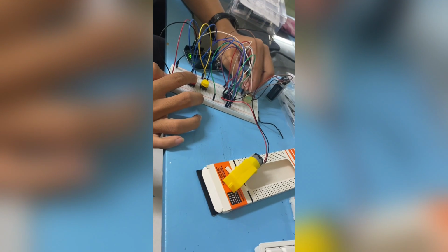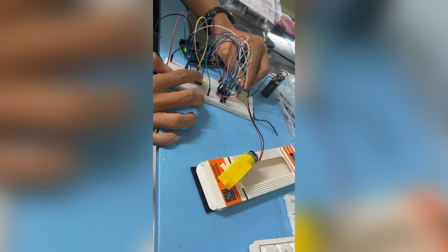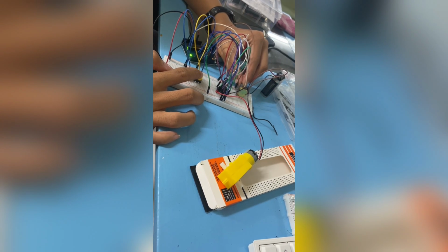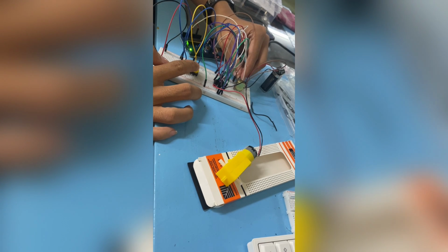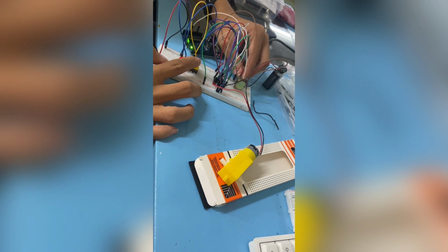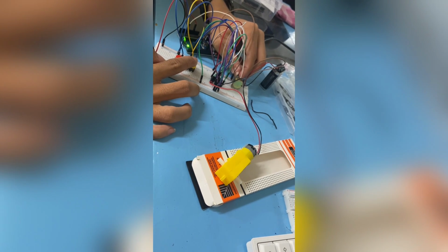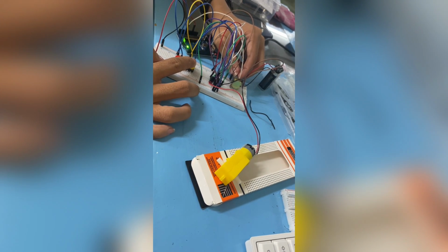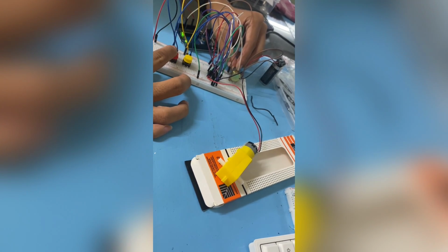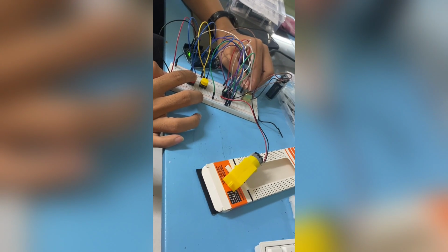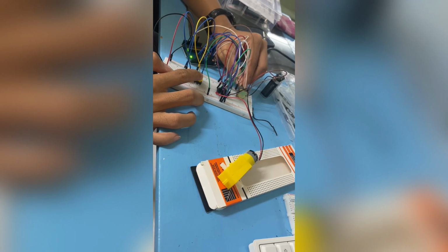This activity combines everything from the former activities. Two push buttons control direction, and a potentiometer controls speed using analog input and PWM output. Together, they allow full manual control of a DC motor's behavior, both speed and direction. This can be applied in robotic arms, in vehicles, and RC cars, for throttle plus direction control.